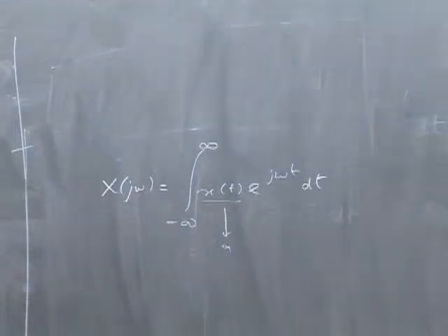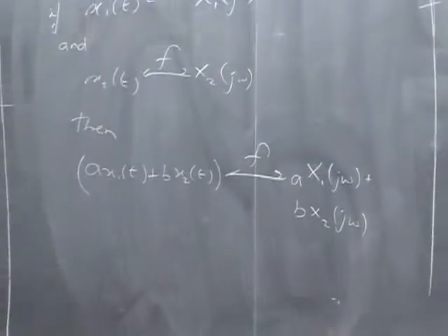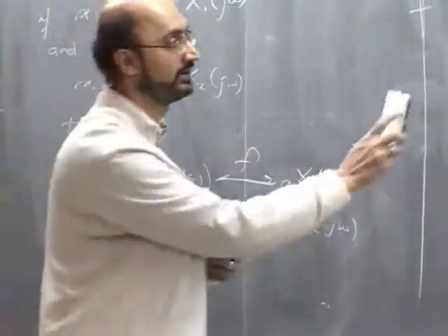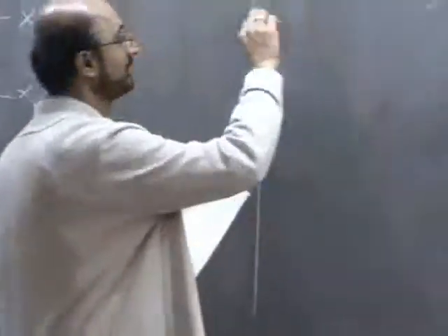So that's where we get that. Similarly, if x of t is replaced by x of t plus y of t, we know that integrals sum up. The area under the sum of two functions is the sum of the areas. Because integrals sum up and because integrals scale, so does the Fourier transform. So we get linearity essentially as a trivial property of the Fourier transform. And we can use this for some interesting stuff.